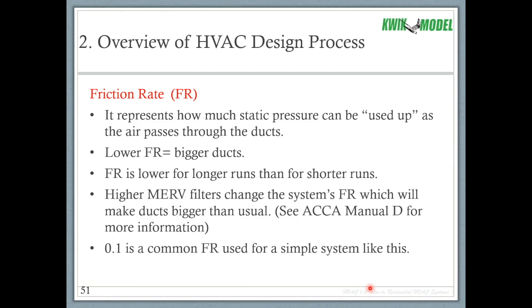Another thing that you're going to have to keep a close eye on, especially out in California, they've just mandated MERV 13 filters in all new systems. That puts a big pressure drop on the system, so you want to make sure that you take that into account. So 0.1 is a common friction rate used for simple systems like this. Again, this is just an example. When you do an actual design, you're going to want to calculate the friction rate for that system, but it'll be fairly close to 0.1.